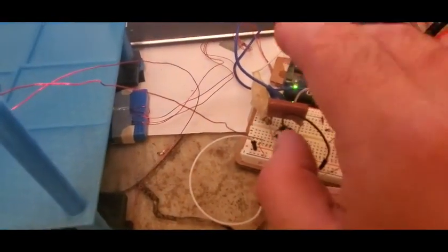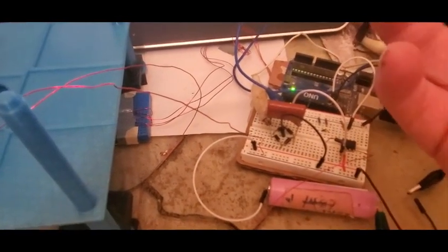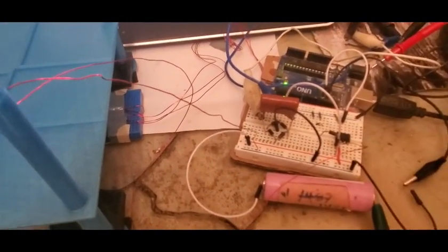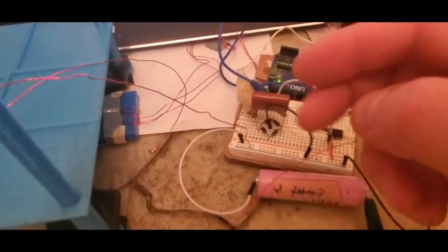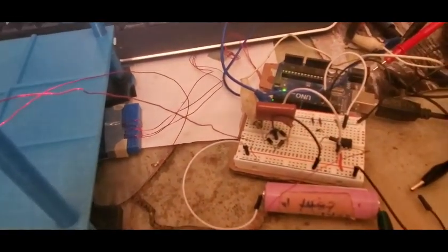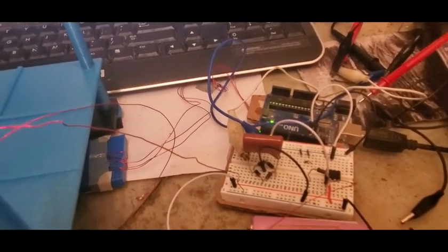And if you're using a resistive load, a reasonable one like 1K, 100 ohm, 10K, it behaves pretty much the same as a single diode. It's just more complicated, and you have a little bit more loss through a second diode. Last thing, and then we'll wrap this up.